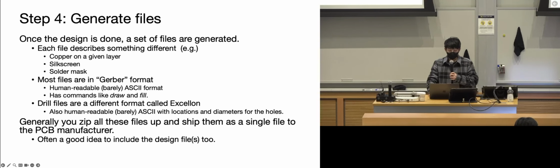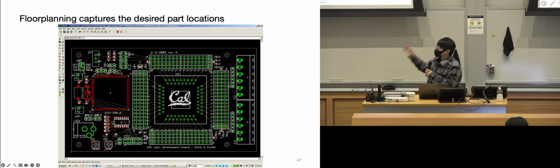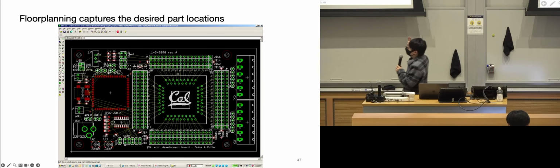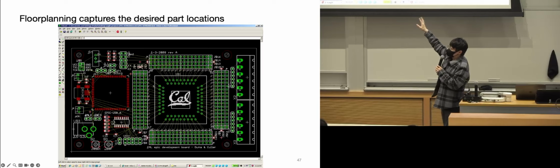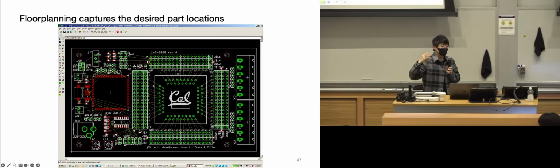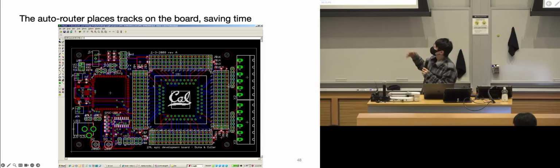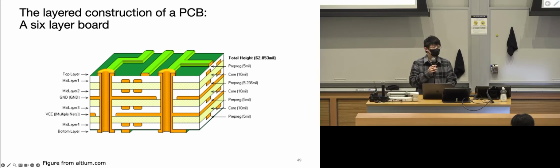So just to give a higher level workflow, you start with a schematic, and this is obviously a way too complicated case. But then you have all the locations placed, and once the locations are placed, all the air wires are still there, showing you the logic connections of any given PCB design, and then you finish the routing. And this one happens to be a 6-layer design board, which is probably too complicated for a while.